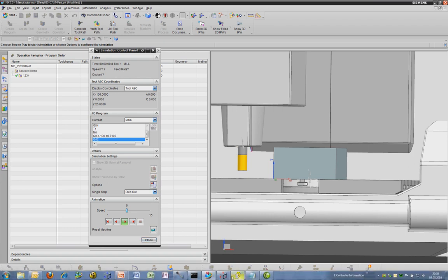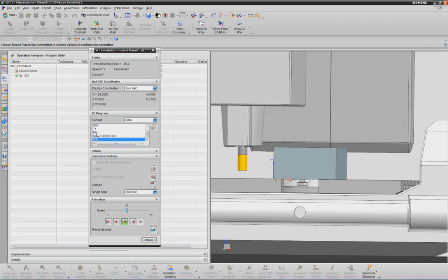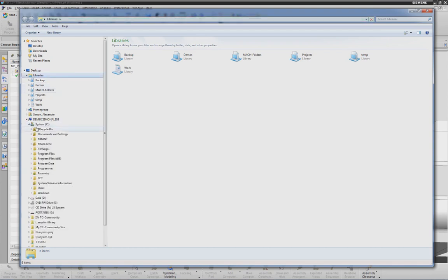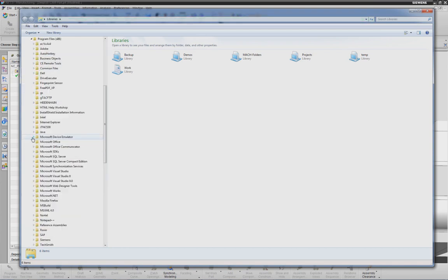So we can either program that here after the M6, but like I told you in the section about the tool length compensation, typically the length compensation on the Siemens controller is activated already in the tool change subprogram. So we can try to locate our tool change subprogram and just add the D1 to activate the length compensation directly there.